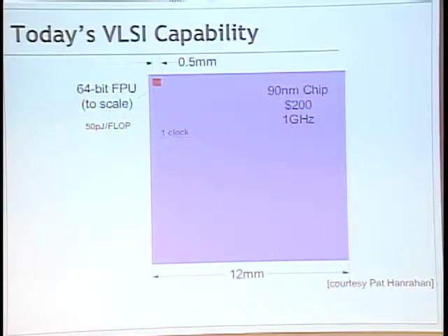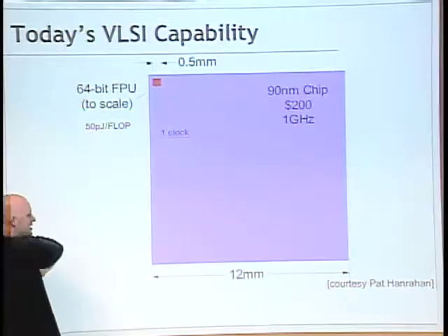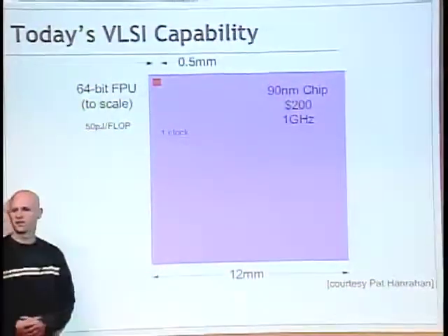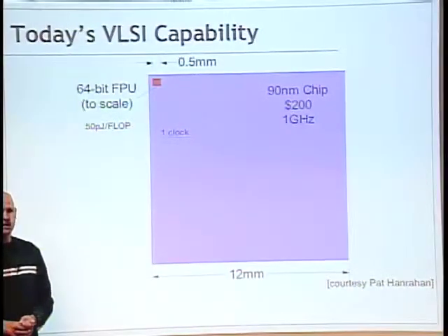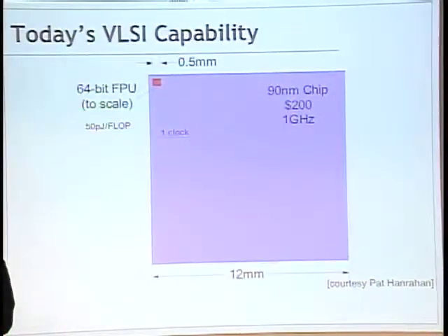So the issues here are that compute is cheap, and communication is getting more expensive. It would be easy to take one clock and send a signal all the way from one side to the other. We didn't have to worry about that. Today we have a clock, and it's going to take multiple cycles to get all the way across the chip. So when I talk about the collision course of technology, this is one of the places where we see this collision: this difference in how computation is changing. Computation is getting really cheap versus communication, and communication isn't changing at all, because the speed of light doesn't change. So these two things are on a collision course, and it really motivates the way we think about technology going forward. We need to build pipelines and structures such that they take advantage of these trends.